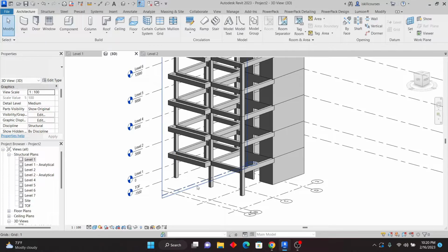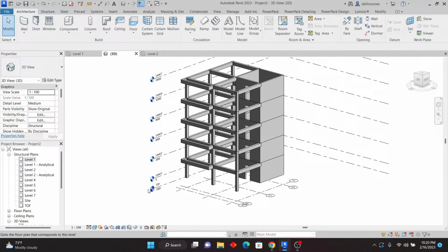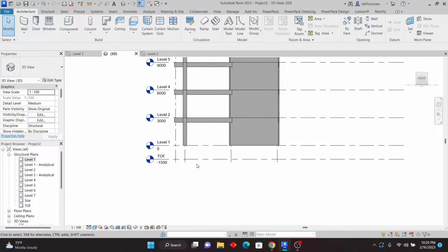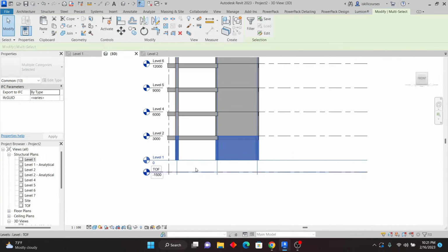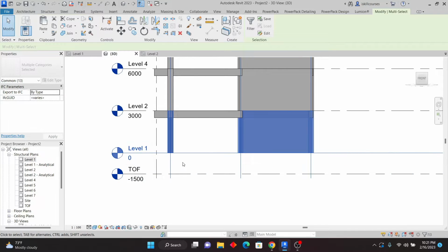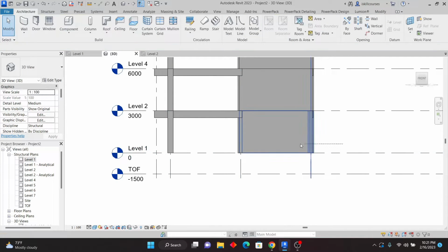Now let's have the bases there, the foundation. All I need to do is go to the front there. You can see that now I also need to create the columns down here and the walls. So what I need to do is select everything from there up to there. This is another trick that you have to use. You can see that the spacing up there is equal, but down here is not equal. We're just going to change the constraints, the top and the bottom, to fit there. So I've selected everything down there, the walls, including the columns. I don't want to select the beams, of course.